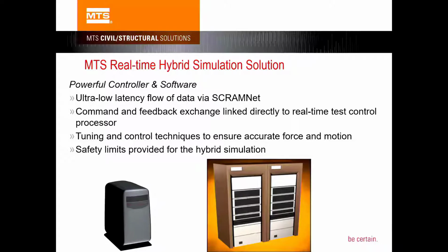In real-time hybrid simulation, again, you have to have a controller. The controller has to have a SCRAMNet card installed inside, and we have different controller types. The actuator has to get the command from the SCRAMNet card in real time.